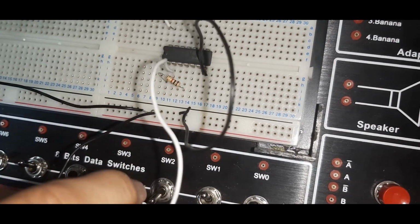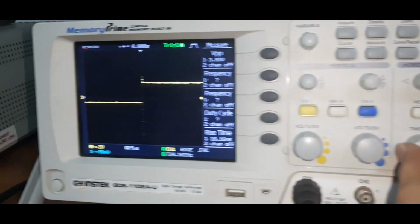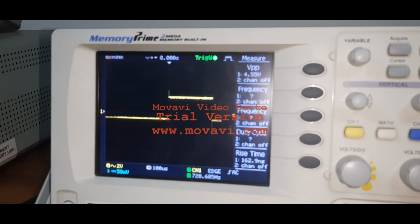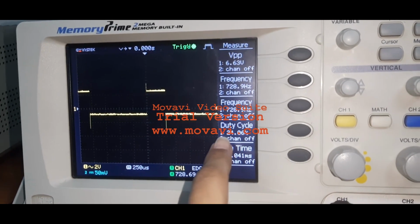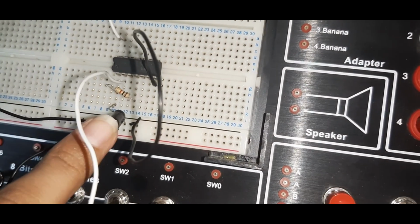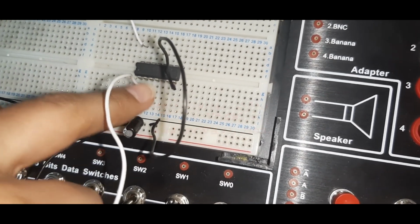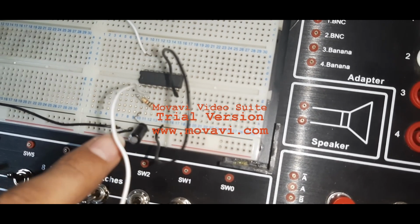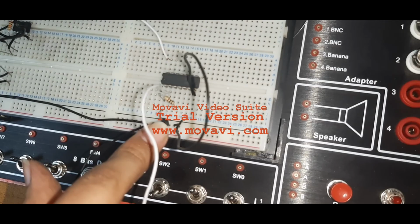If I further change the capacitor to 1 microfarad, then again the value of the frequency of oscillation will change. Now it is in hertz, while the duty cycle will remain the same. So we can conclude that the frequency of oscillation depends upon the value of the capacitor that we use here, and the duty cycle will depend upon the resistor that we use here. And it will behave as a square wave oscillator because it is producing the square wave.